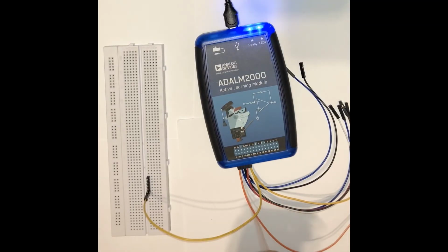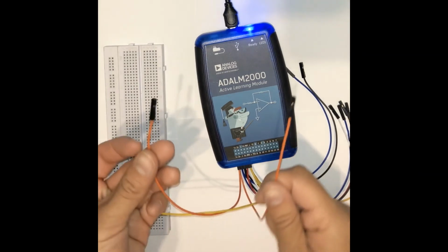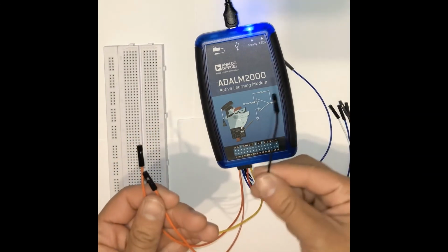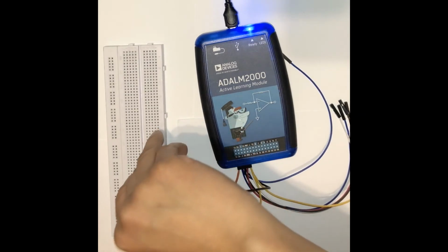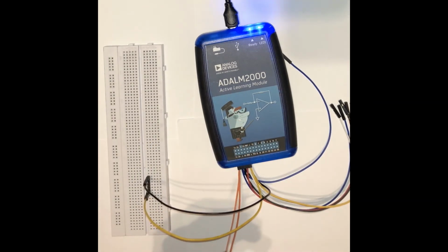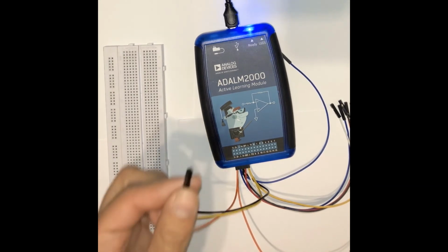So in order to confirm that the signal generator is functioning properly, we can use the oscilloscope, which will display a graph of voltage over time. And so we can check and see if that signal, that sine function, was properly generated. So we can use the same breadboard setup in the previous example, and we will use the orange wires and a ground wire to use the oscilloscope to measure that signal.